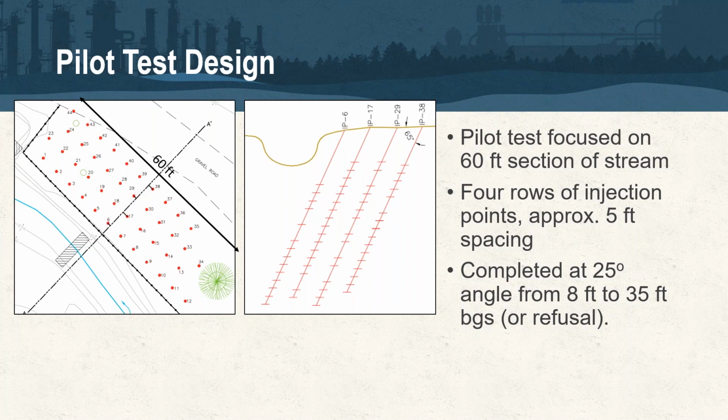Essentially, just trying to install through a cased well is going to get caught by the filter pack and/or fill the existing casing. So all the points that Mike has talked about here in the overburden scenario are temporary dedicated points. And if we're working in consolidated lithology, we do need to have open boreholes.